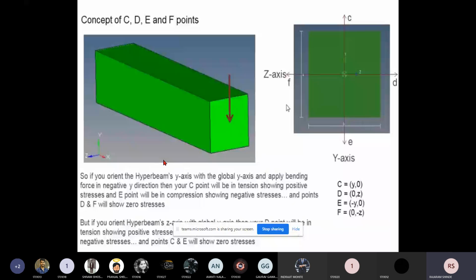Now in theory of bending, what have you studied? Here you have the neutral axis at this location. Am I right? If you have this beam and it is fixed at this location, and we apply the load at this location, it will deflect like this. Do you agree with this? And whatever bending stresses you got in this beam, the upper portion of the beam is subject to tensile stress. Am I right? As it is a cantilever, the lower portion is subject to compressive stress.